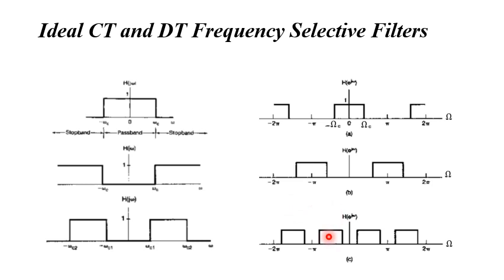A similar argument applies to the band pass filters in the discrete time. So in general, you understand that in the discrete time case, the responses of the filters are also periodic. In part C on the right side here, the ideal graph for the band pass filter is shown. These are the frequencies: this is the lower cutoff frequency, and this is the higher cutoff frequency. So the response is also periodic.